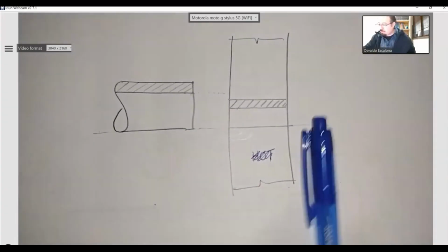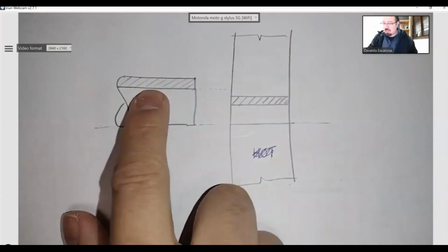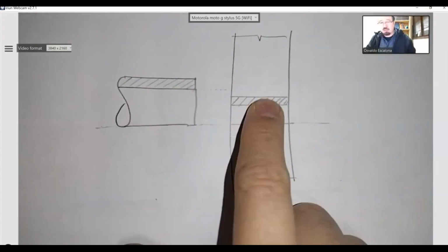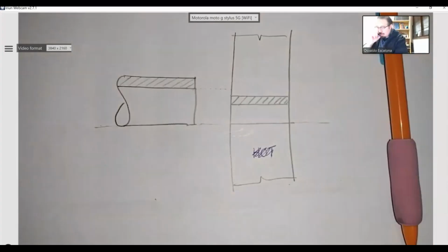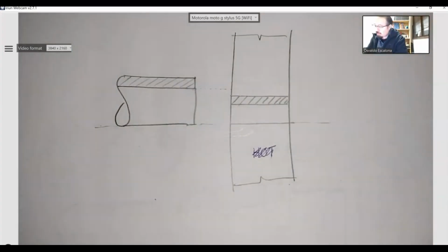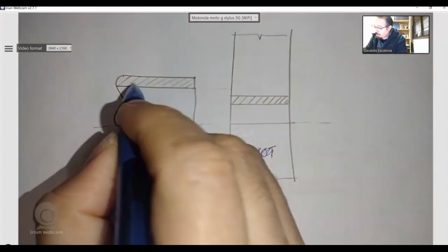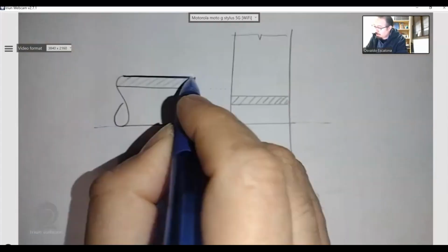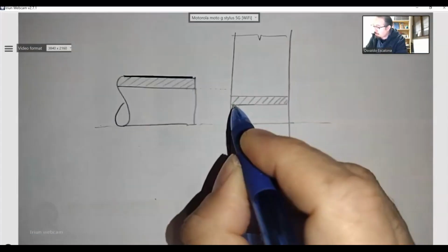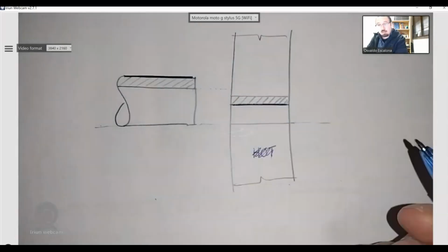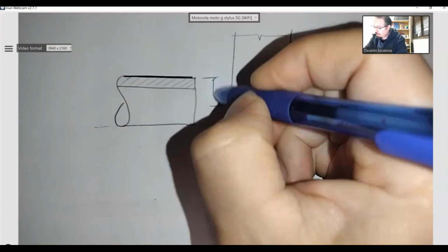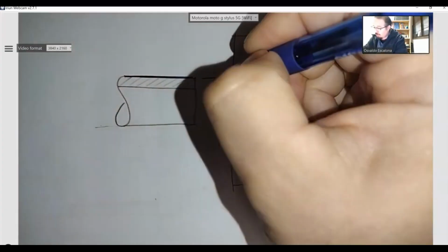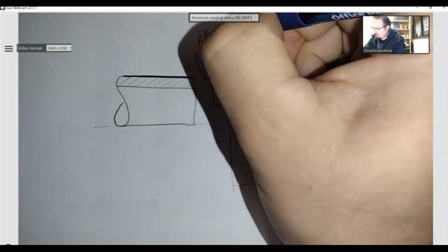Okay, how do I do? By the way, all of this we'll talk about, how we determine the allowance and the clearance, the tolerance, next time. For now, we just gotta understand what is happening. Okay, so let's say what is the worst case mating condition? Well, the worst mating condition is when my shaft is the biggest and my hole is the smallest, right? It will be super hard for this guy to go inside of it. This little distance is what we call allowance, as I previously told you.